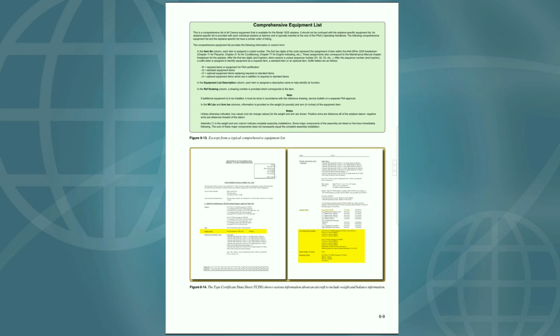Airspeed limits: VNE, never exceed, 217 miles per hour, 188 knots. VNO, maximum structural cruise, 190 mph, 165 knots. VA, maneuvering, 4,200 pounds, 146 miles per hour, 127 knots. VA, maneuvering, 4,000 pounds, 146 miles per hour, 127 knots. VA, maneuvering, 2,743 pounds, 133 mph, 115 knots.